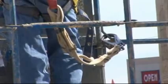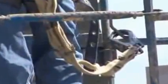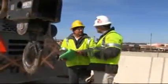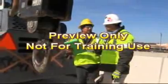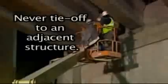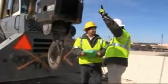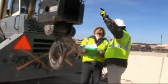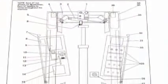Most lifts contain a restraining point which is designed to attach to a personal fall arrest system or restraining device. If no anchor point is available, it is up to the on-site job supervisor to determine the best point to tie off. Tie off to an adjacent structure is never allowed due to the possibility of being pulled out when the lift is moved. Your employer and the manufacturer of the lift in use will provide more precise fall protection rules and guidelines.